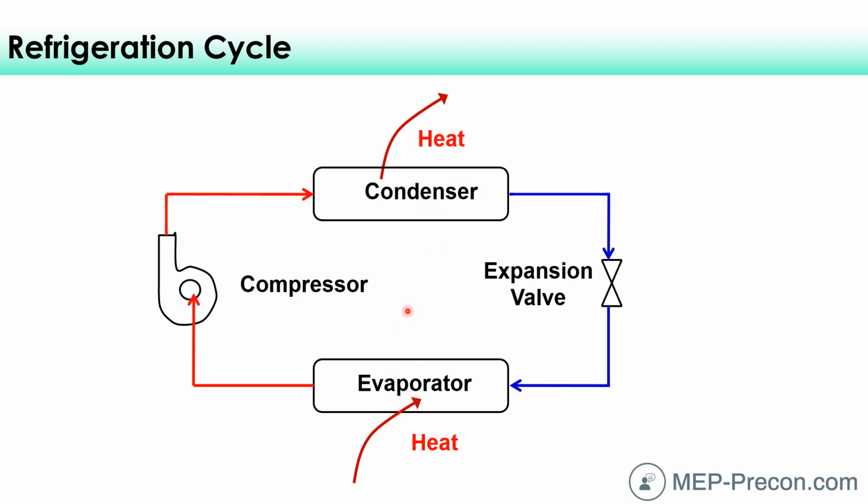We're going to be in air conditioning mode here. We're going to talk about that for the majority of the rest of this video. At the very end, we'll talk about a heat pump. But for right now, let's talk about air conditioning, meaning we're going to remove heat from the building. And we're going to do that with an air coil here. On one side of this coil is refrigerant, and on the other side is air. Same thing with the condenser.